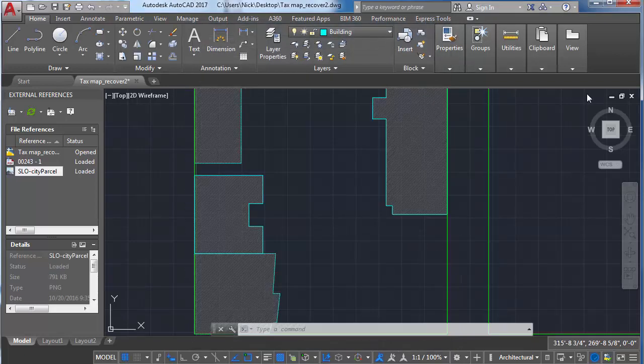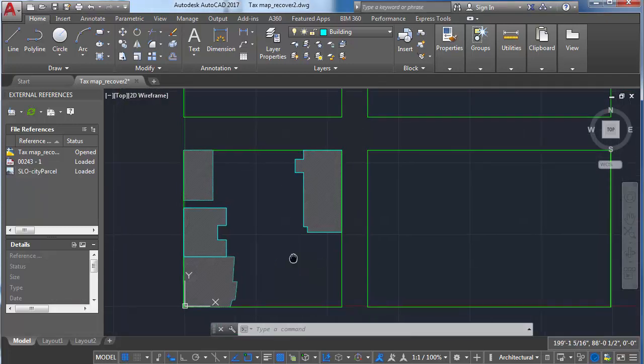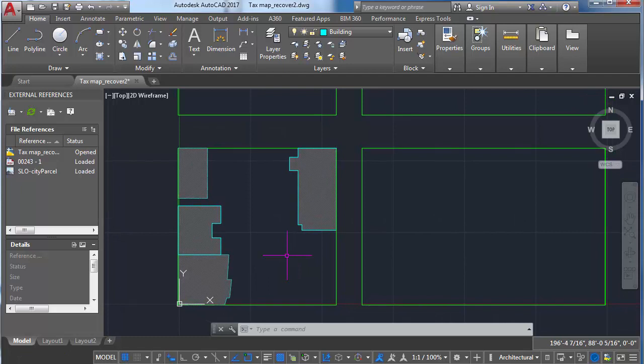You're well on your way to completing the figure ground map. This is a good time to save your file. Once you've finished tracing and pochéing the entire site, you can print this building using the method we went over earlier in our video tutorials by creating a new layout and selecting the annotation size you'd like to use and viewing a print preview.